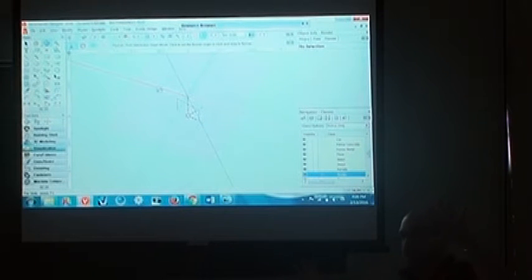I need a surface that is at some odd angle, and I want to be able to draw on that surface and extrude from that surface. So by setting a custom working plane, that gives me a surface that I can work on. And if I were to start drawing now, I would be drawing on this surface, on this plane that I just created.